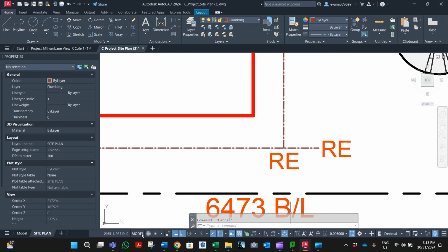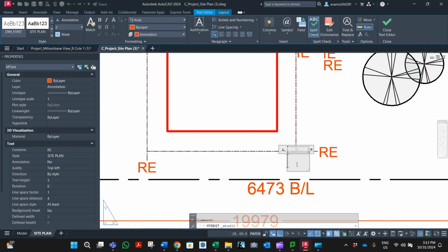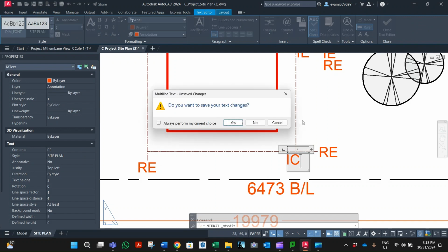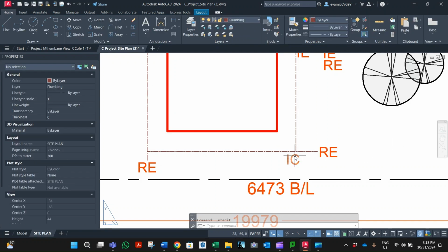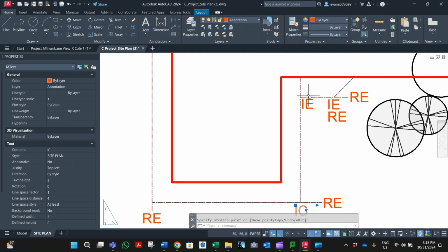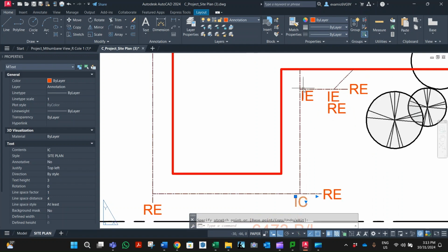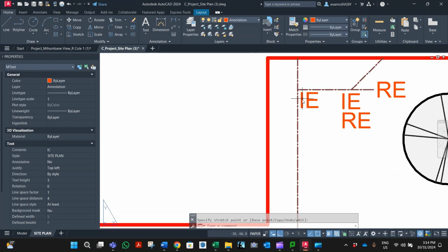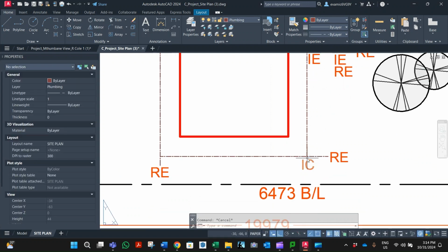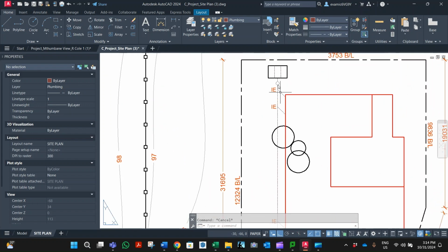Oopsie, I've clicked into it here, so I need to go back out into my model space so I can zoom in and out. I want to make sure that I can inspect that section, because the rodding, which I probably could bend around this corner, there would probably be a 45 here and not necessarily a T section, but in saying that, it's probably wise to have a T section. So the inspection chamber here, I think, is good so that if we do need to rod, we can rod from the inspection chamber up that way. Good. So all in place, looking good.